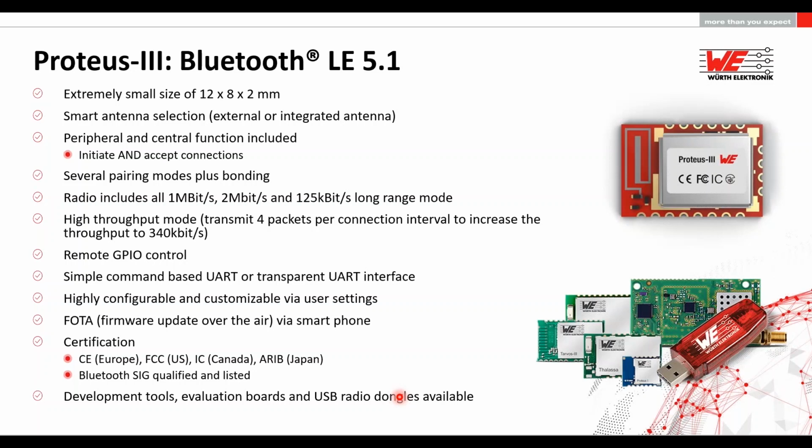Now the Bluetooth variant, the Proteus-III. Other than having the same physical size and the features with respect to smart antenna selection and these hand solderable pins, the Proteus-III offers a complete Bluetooth stack on board. So you don't need to have some kind of Bluetooth stack running on your host microcontroller. All you need to do is implement the command interface and interface it with the UART, and you're good to go.